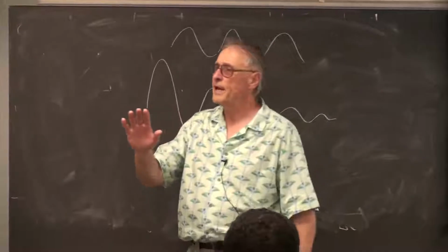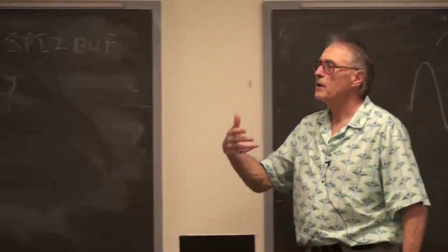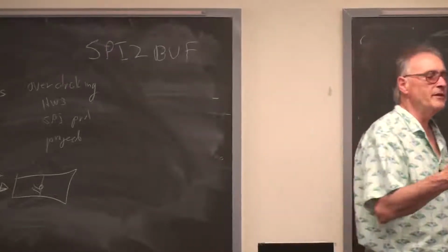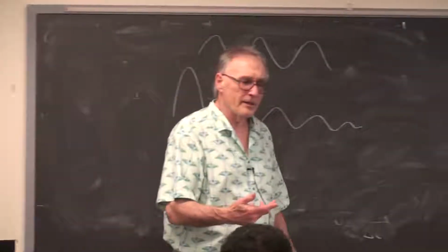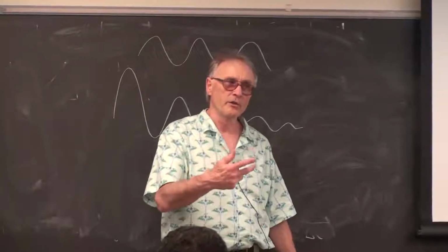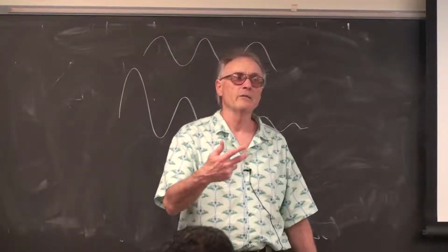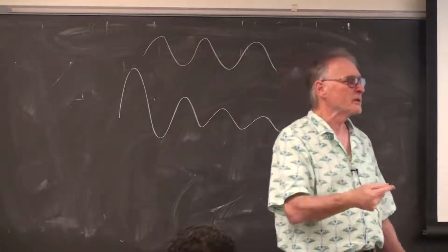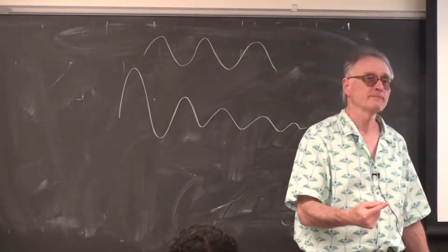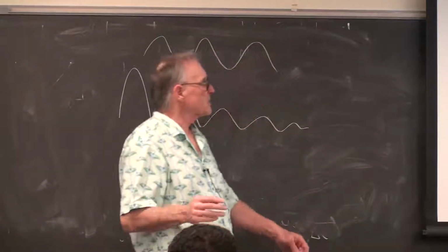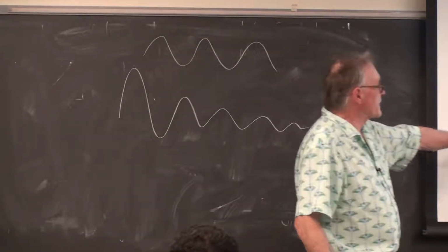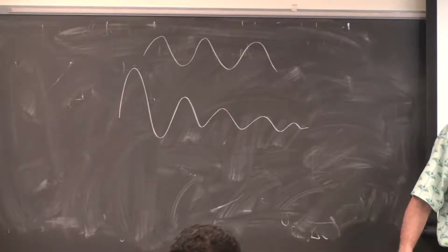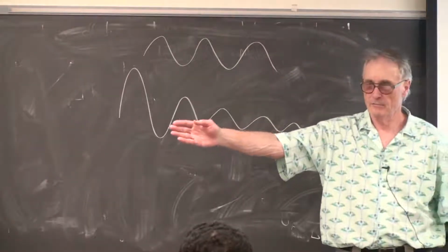There's the interrupt flag that the interrupt controller notices and deals with, and then there's an event flag that the DMA controller can use, which is always set regardless of whether the interrupt is turned on for the timer or not. So this says, notice when the timer times out, do not take an interrupt, just start the DMA channel.